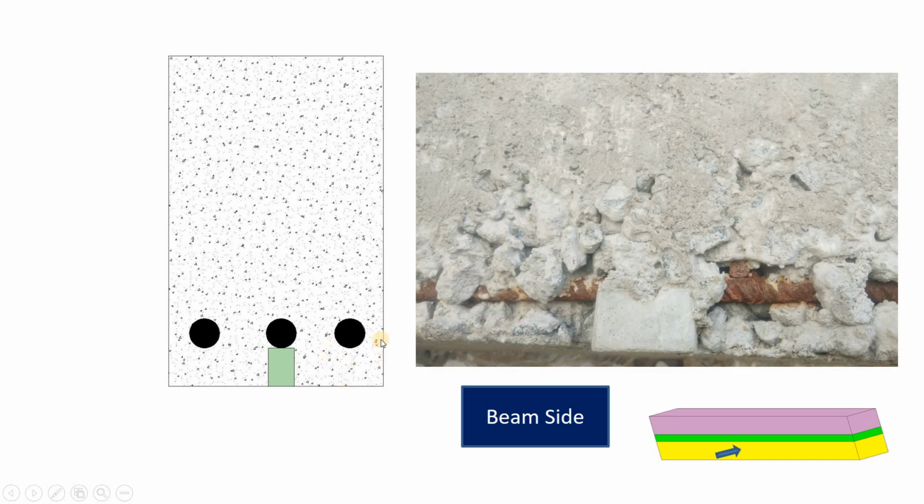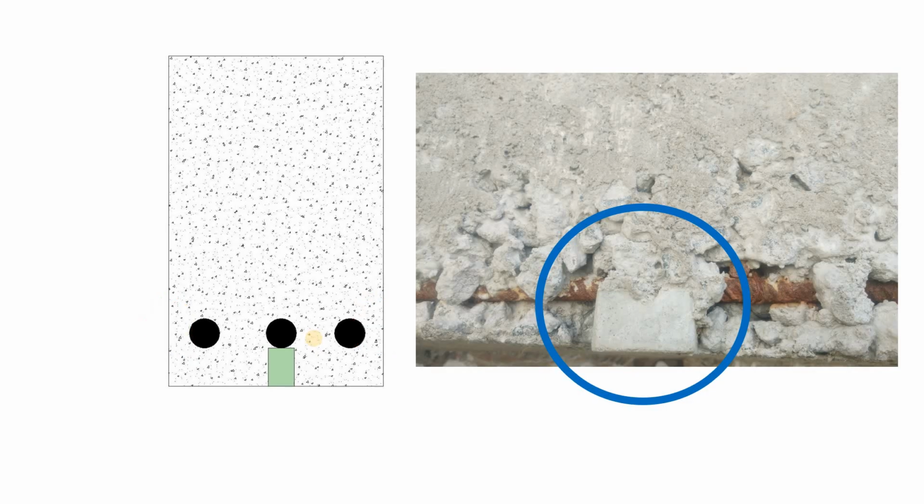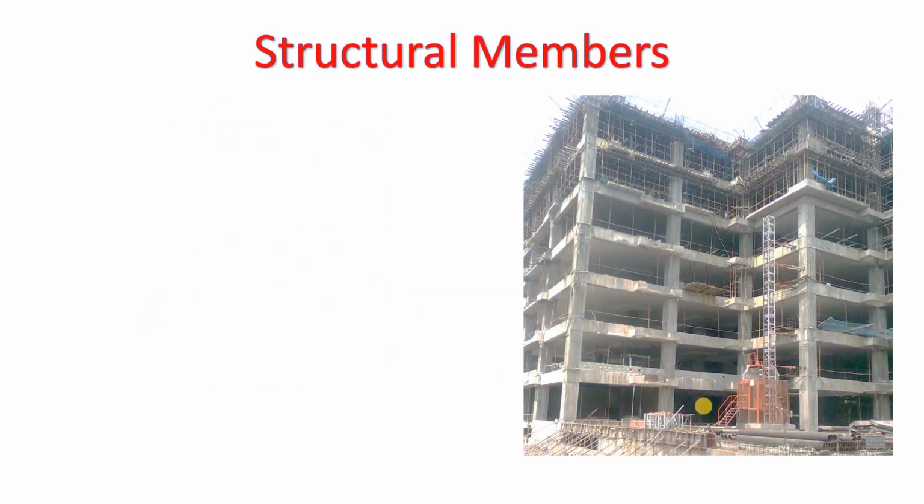The reinforcement bar must be protected in such a way that it is embedded in a very good manner, and also the stresses are balanced so that it is not away from the extreme fiber and it is not towards the neutral axis zone. Therefore, these regions also must be taken care of so that the reinforcement bar is kept properly embedded in the concrete. This is taken care of by reading IS 456-2000.